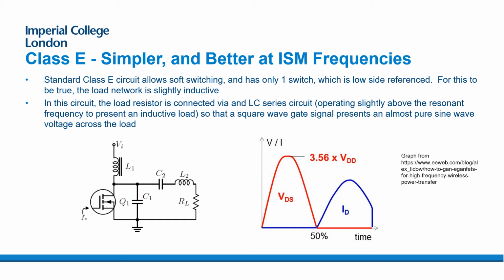Single switch inverter, as you see on the left here. There's a resonance circuit that is hanging off the inverter. The input part of it looks a bit like a boost converter, and as long as you're switching the transistor at the right frequency as a function of the resonant network hanging off it, we're pushing current in through L1, and we're getting a nice resonant action here so that we're producing a sine wave in L2. L2 here is the transmit coil. RL is the load that is being reflected from the receiver back onto the transmitter.